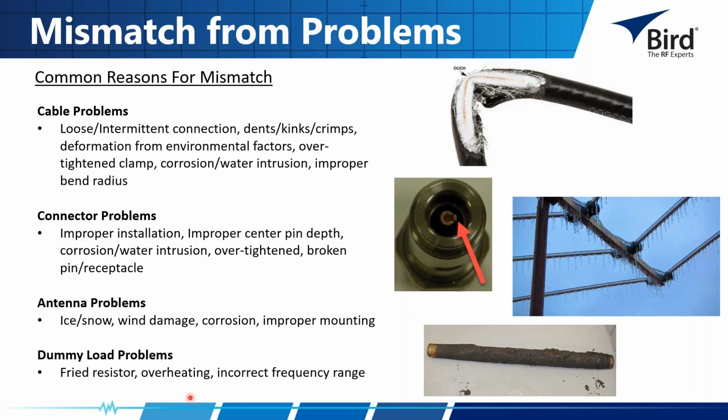And as we were looking earlier, we were trying to lock our sensor into that smaller temperature band to kind of pull the uncertainty in. So now if we're really dumping a bunch of thermal energy into that sensor, we can expect to now be sort of going outside of that 15 to 35 C like we saw earlier. So I've seen that lead to some accuracy issues as well.